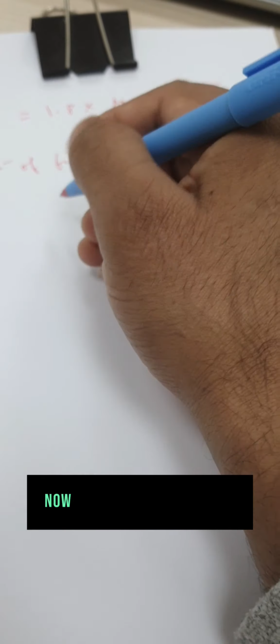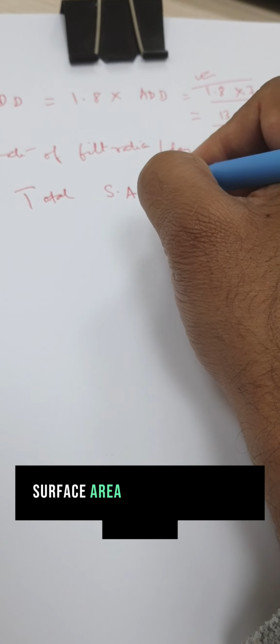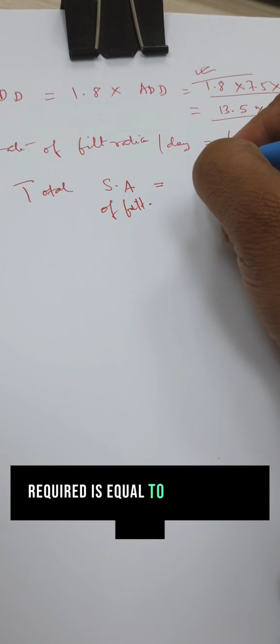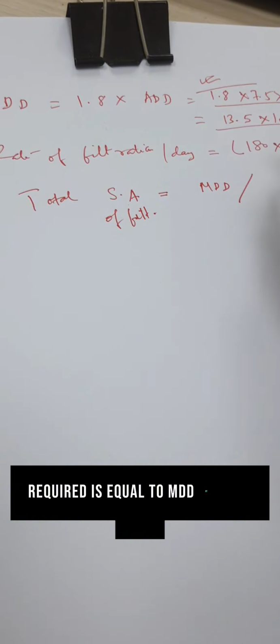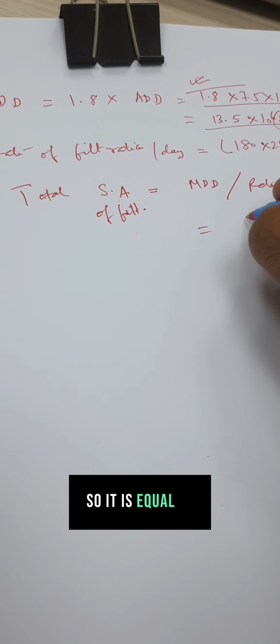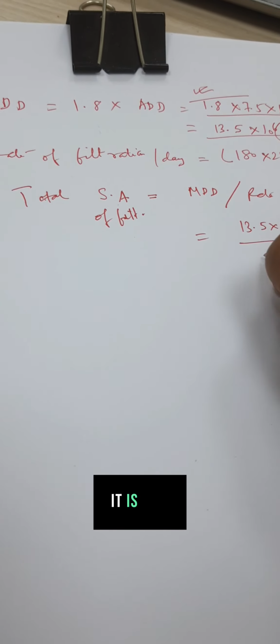Now we know that the total surface area of the filter required is equal to MDD divided by the rate of filtration per day. We have already found the MDD.